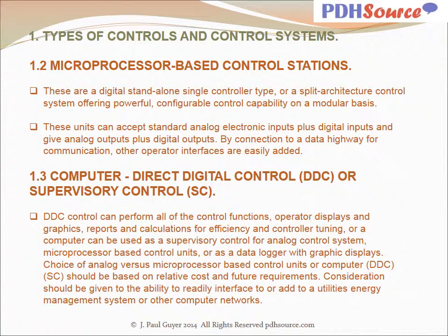Microprocessor-based control stations are a digital standalone single controller type or a split architecture control system offering powerful configurable control capability on a modular basis. These units can accept standard analog electronic inputs plus digital inputs and give analog outputs plus digital outputs. By connection to a data highway for communication, other operator interfaces are easily added.